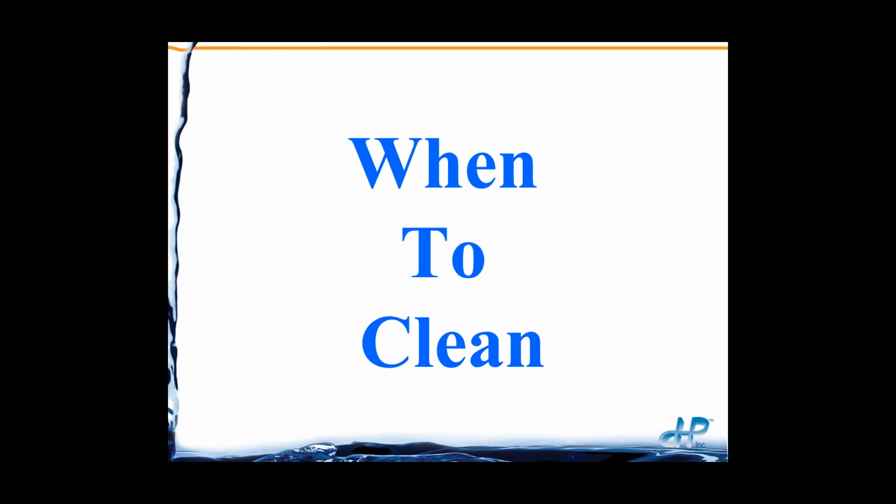So as long as we keep an RO unit at the proper recovery rate and our softeners are operating properly, or I shouldn't say and or, our scale inhibitor injection is operating properly, then scaling shouldn't be a problem. So when we do scale, it usually means that there's been some upset, or we're at a higher recovery than we really think we are, or the feed water has changed, and then we scale and it'll be time to clean.